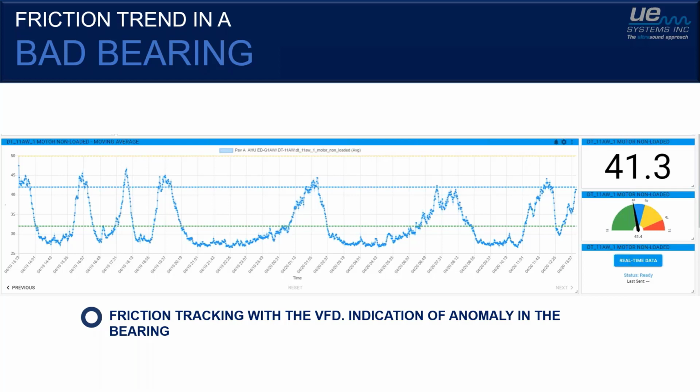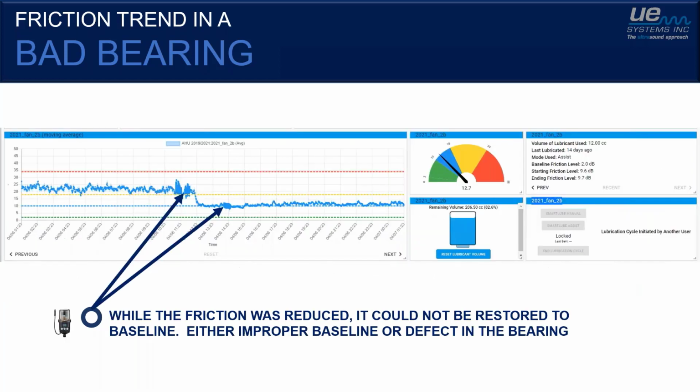And if you remember the same fan I was showing you before through the same speeds, it didn't change by more than 2 or 3 decibels. In this case, we're looking at possibly a 15 decibel change. It's not uncommon to first put the sensor on and see this roller coaster of a ride. I'm going to say, apply a little bit of grease for me, right? And then the roller coasters start to be not as fun anymore. They start to even out, and eventually they'll get smooth.